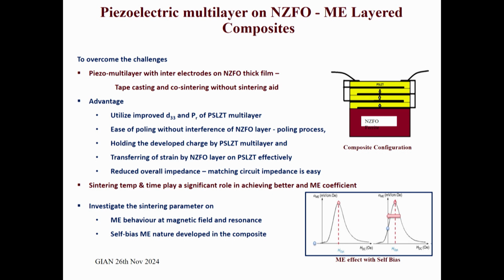Now, here these layers are electrically parallel with each other, but mechanically in series with each other, and therefore you get improved performance. See, as far as the miniaturization of the device is concerned, what you need is a very thin device, but if you go on thinning the device, the piezoelectric performance is diminished. Now, how to compensate this is to make layered composites.